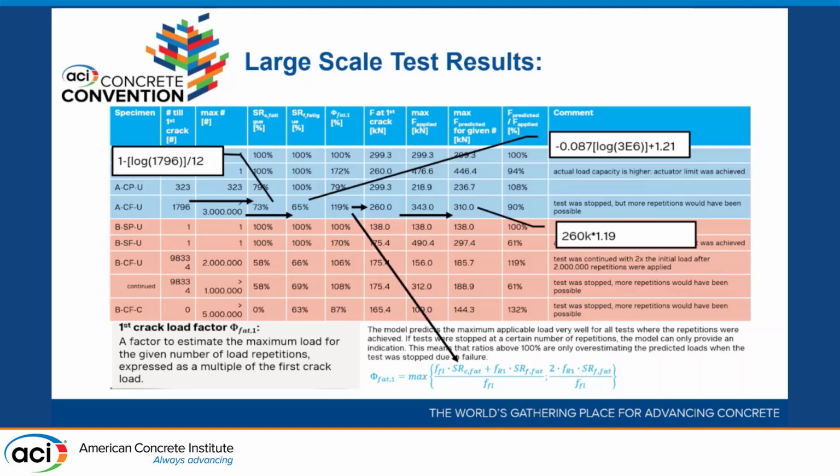So this model predicts that particular specimen at 90% of the maximum number of cycles that section would be able to carry at these given intermediate stress levels. You can see here that it's not bad. Some of these are a little off, but we're hovering right around 90, 100%. Good overall predictability of the model. Keep in mind it's simplified and trying to be practical.